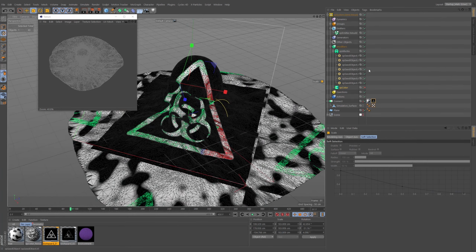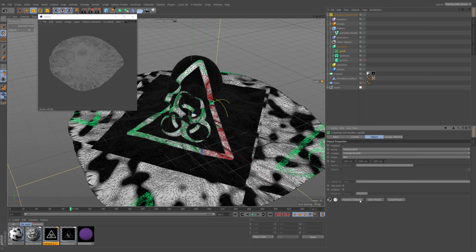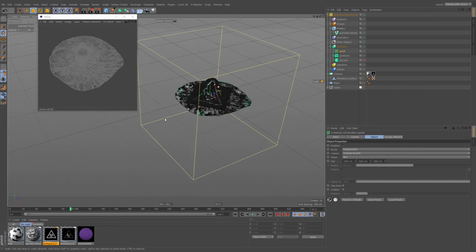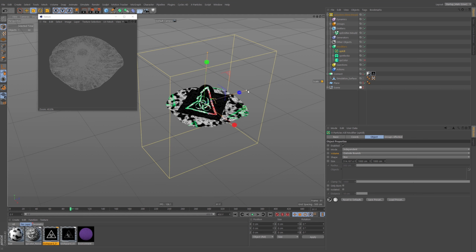I think actually one way to solve it would be to just kill off these particles that are outside this boundary. So we could just use a kill object modifier. So let's do that actually. Let's go to modifiers, control modifiers, kill. And you'll see we get this bounds. And essentially, in the default operation, anything outside the volume, anything outside the bounds will be killed.